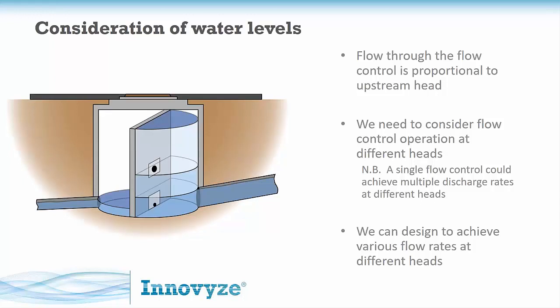So it's typically going to look something like this. As Chris mentioned, I'm going to go for a parallel approach. So I'm going to be designing with flow controls in the same chamber to one another. If you wanted to implement a series approach, then I'd just do that in MicroDrainage by dropping flow controls on different manhole locations, so maybe 2 consecutive controls, and we could design each control separate from each other and then look at their combined behaviour to ensure that we're achieving a series approach. We're going to do a parallel one though today.